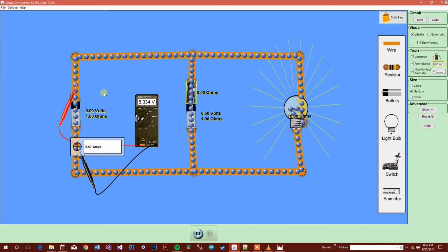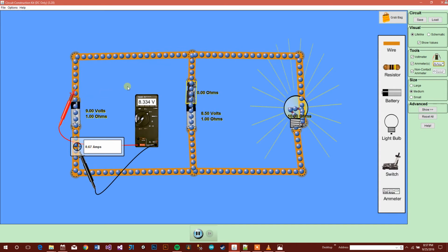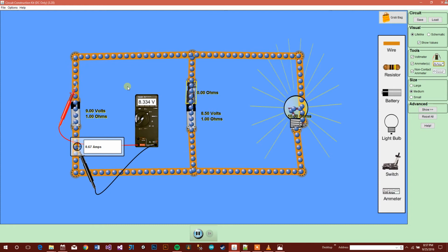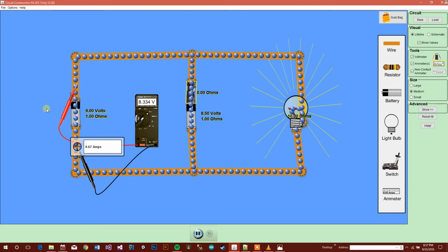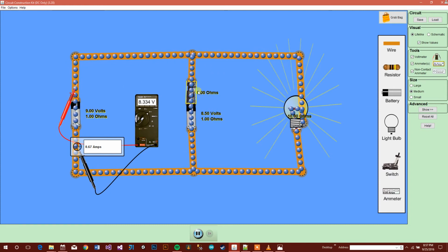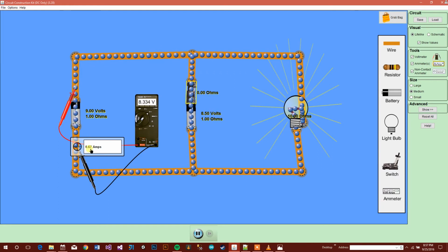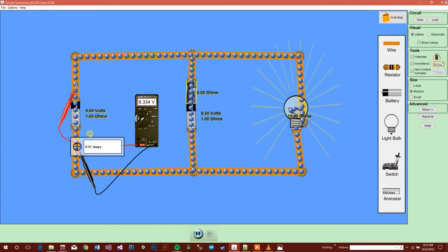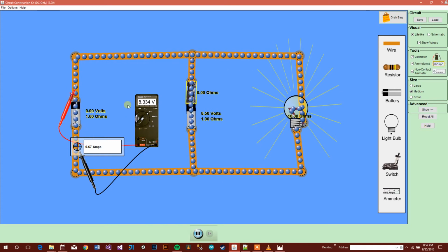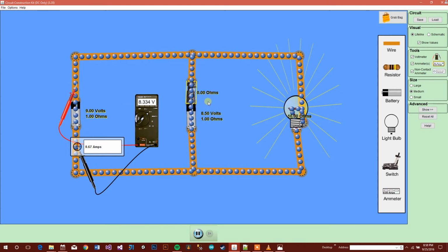As you know, the voltage drop is equal to the EMF minus IR, the internal resistance times the current through the battery. So in order for that second term to become less, the current would have to decrease in the battery, and so you get a higher voltage coming out of this battery.